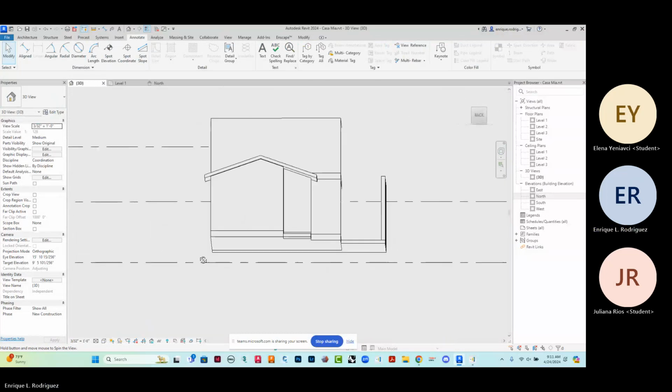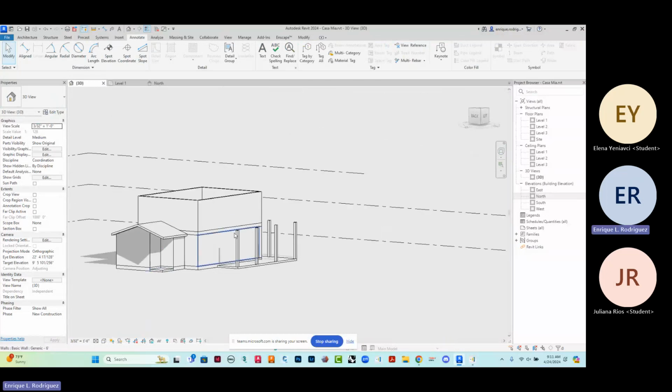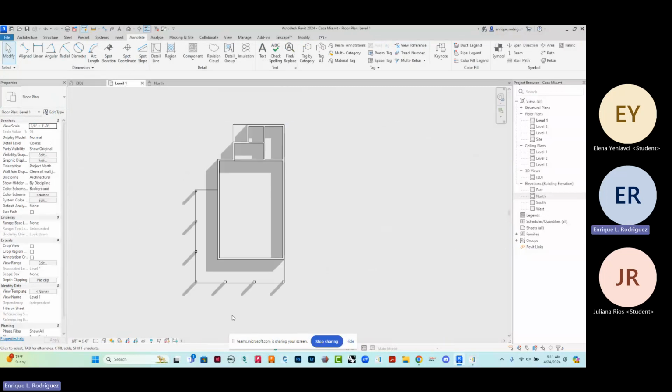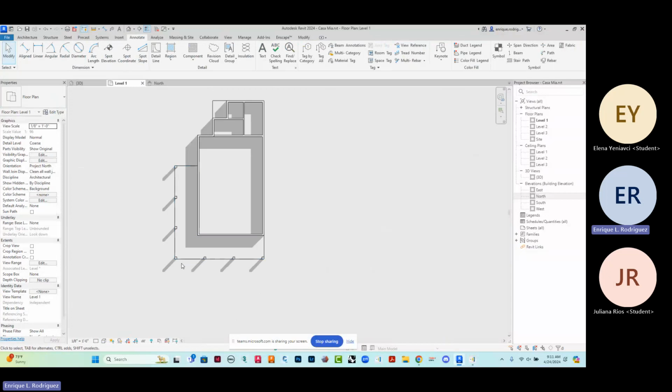Okay. All right. I'm going to go ahead and do the porch roof along the front also. Now, the height of the porch roof is going to be determined by a couple of things. We're going to go ahead and do it at 9 feet to match the other one and then lower it accordingly based on this 8-inch column.